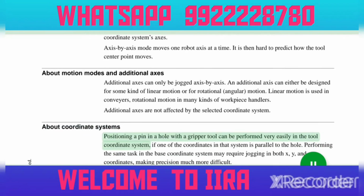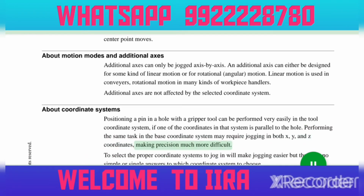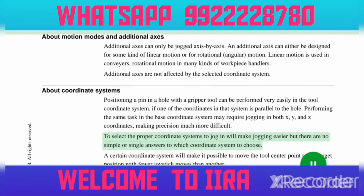About coordinate systems. Positioning a pin in a hole with a gripper tool can be performed very easily in the tool coordinate system, if one of the coordinates in that system is parallel to the hole. Performing the same task in the base coordinate system may require jogging in both x, y, and z coordinates, making precision much more difficult. To select the proper coordinate systems to jog in will make jogging easier, but there are no simple or single answers to which coordinate system to choose.